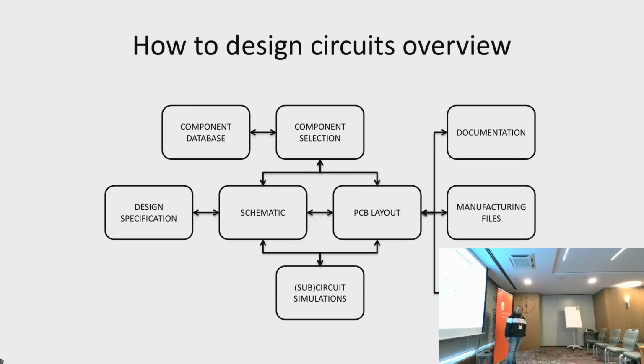Also in that case you might require some simulations. When your PCB layout is done, you generate documentation, manufacturing files, and the PCB 3D model. It might happen that you get feedback from the manufacturer or from the mechanical engineer that uses your PCB 3D model for the enclosure, so you need to go back to the PCB layout. So maybe you need to add other components to your database to put them in the schematic. So it's a bit of back and forth till you have everything ready and verified to move forward with production.